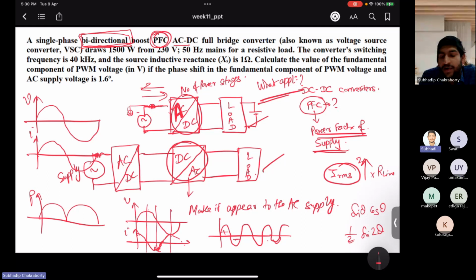Yes, sir. For that you need just a simple DC-DC converter, right? Or AC-DC also you can do. So both are possible. So there no supply is there. Actually, supply becomes DC. Okay. So the reverse scenario is there. Supply is DC because you have the battery, and you are running some synchronous motors or IPMSM, such that whenever regenerative, you can use regenerative action to slow down the vehicle. Whatever he told, to utilize the energy of the wheels to charge the battery, because